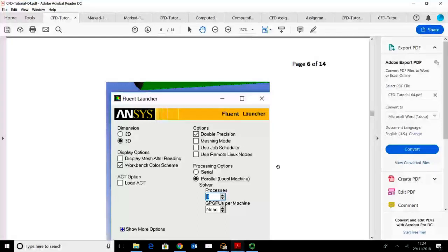One thing that I have to tell you before starting the ANSYS setup is that once you have created the geometry, the next thing that you have to do is to update your ANSYS Workbench. Go to ANSYS Workbench and right click if you see something that is not a tick, and then it will update what is in there.